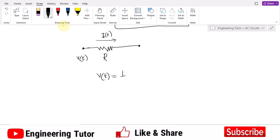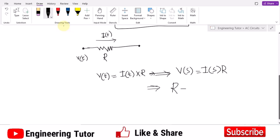According to Ohm's law we have V t equal to I t into R. Converting this into the Laplace transformed version, I will have V of s equal to I of s into R. Or from here we can very easily see that R is equal to V s divided by I of s. So here we can see that in the Laplace transform the value of the resistor will remain the same.